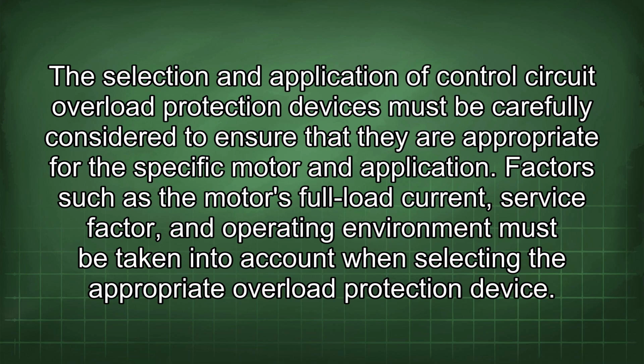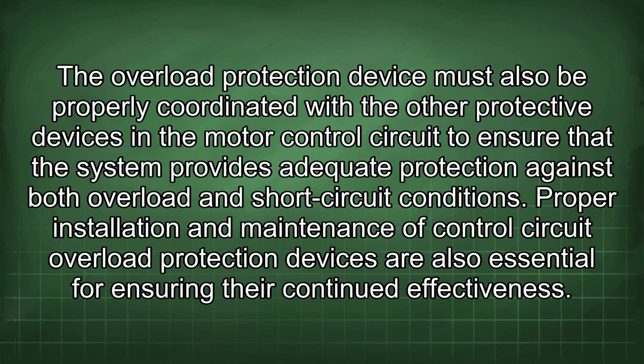Factors such as the motor's full load current, service factor, and operating environment must be taken into account when selecting the appropriate overload protection device. The overload protection device must also be properly coordinated with the other protective devices in the motor control circuit to ensure that the system provides adequate protection against both overload and short circuit conditions.